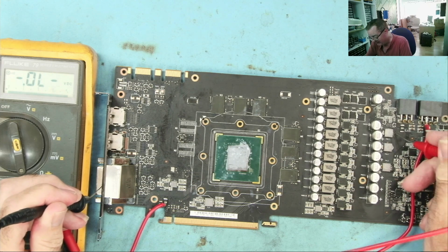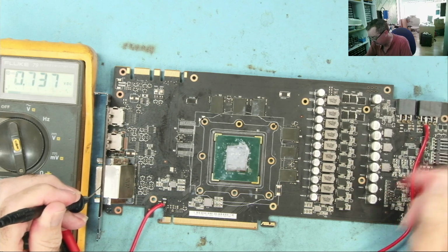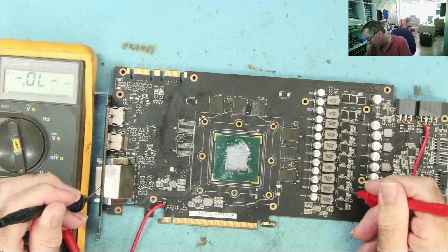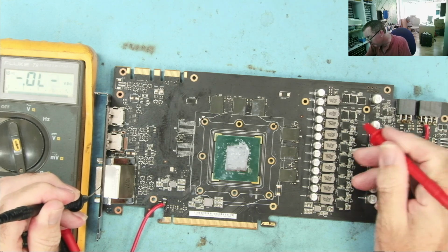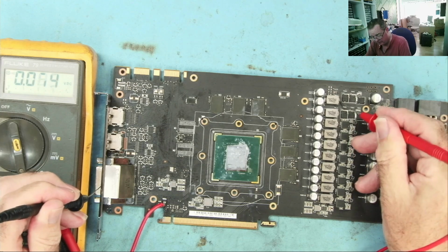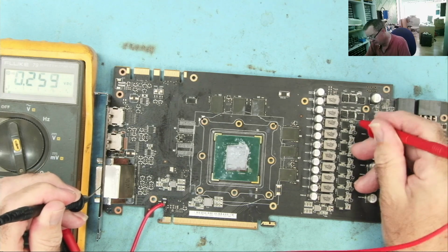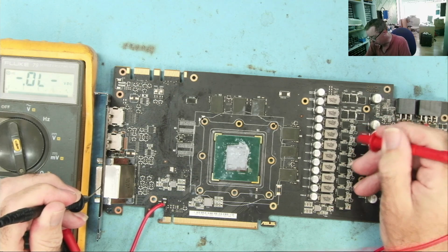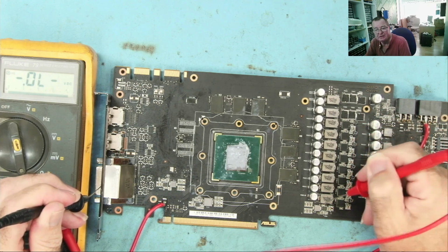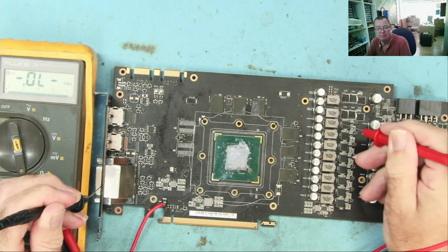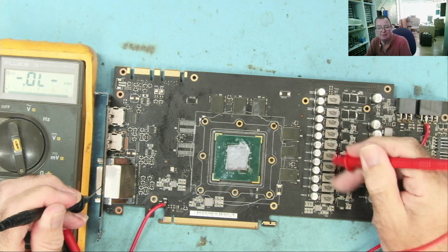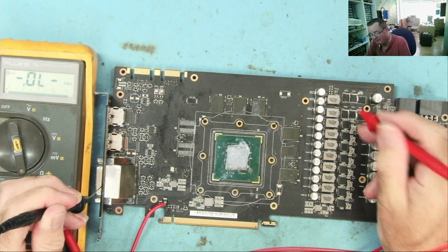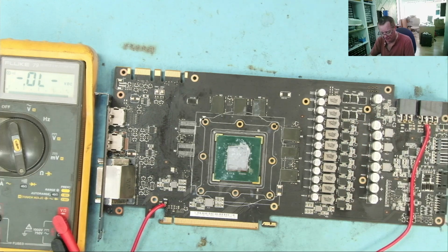Those become like diodes, junctions. These ones will look like a short. Absolute short, dead short, yeah. This one's a little bit higher. A little bit higher. Dead short. So 1, 2, 3, 4, 5, 6, 7, 8. These are all in parallel. These are multiple phases on one voltage regulator module, okay? These are different ones. Let's look at those shorts in resistance mode.